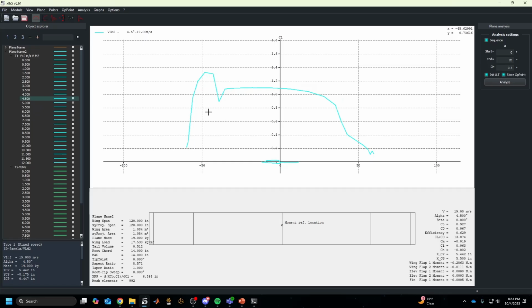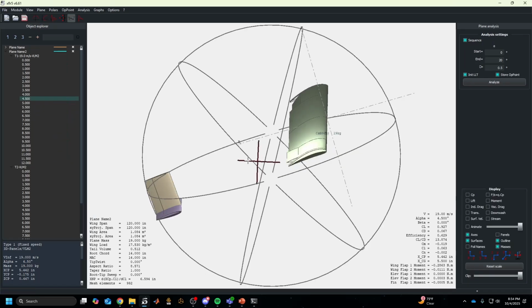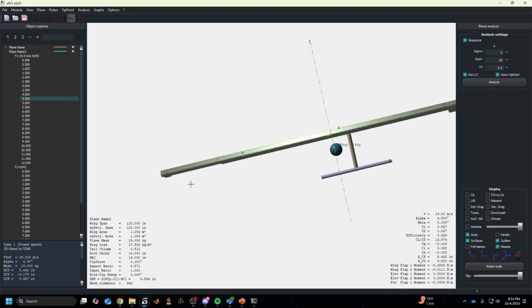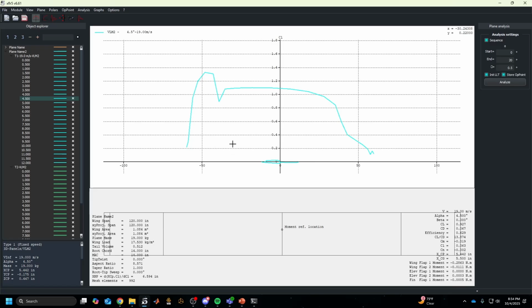So you can see on our, well, this would be our right-hand side, right, if we're looking at the front of it. So this is technically our right-hand side, even though it's the left, because we're looking at it opposite, straight on. You can see our lift here is much higher, and then it's actually significantly lower on the left-hand side, right? So this is why our plane would roll in real life, is because we have so much more lift on the right-hand side of the plane. That's how ailerons work, right? They change that camber angle, they give you more lift.